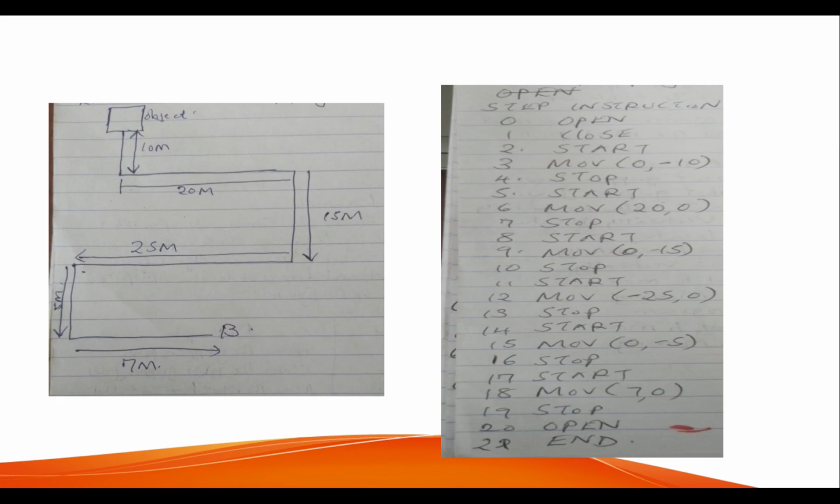After starting, it has to move 7 meters, which is to my right. So it means that the 7 meters, it's a positive movement based on that stationary point. So I'll move 7 because the x-axis is the one that is being affected, but my y-axis remains 0. Then it stops. After stopping, it opens the gripper jaw. Then the program ends. Once it has opened, it means it has placed that object at point B. So that is how we write the program for that